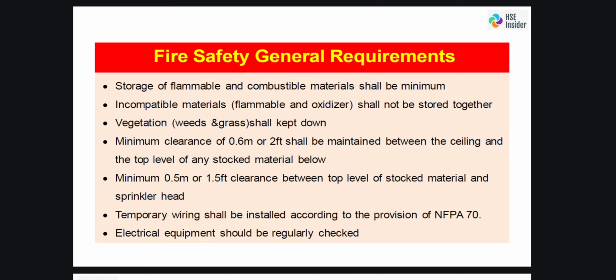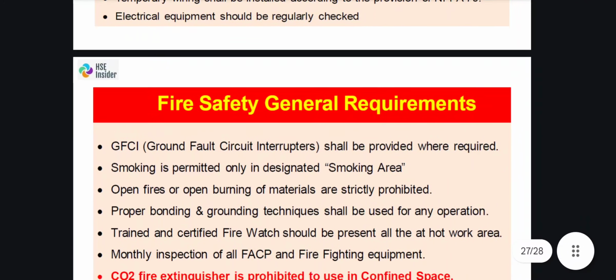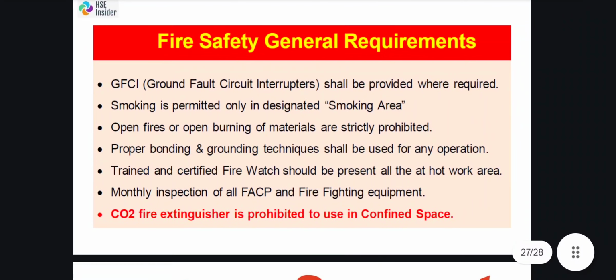Temporary wiring shall be installed according to the provisions of NFPA, National Fire Protection Association, 70 standards. The electrical equipment should be regularly checked by a competent authority. GFCI, ground fault circuit interrupter, shall be provided where required, done with a study by an expert.